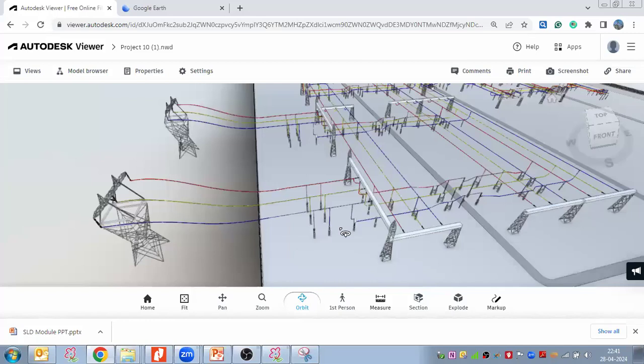Now, since you were talking about the 1.5 breaker scheme, we have discussed that we have 3 CT scheme, 4 CT scheme, and 6 CT schemes, right? So you have to see which CT scheme you have followed. If you have taken the metering CT and metering VT, then they would be required.